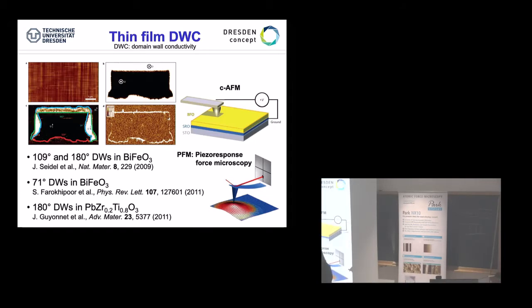This is again the in-plane polarization, and then we have a conductivity map of this one. So he uses two combinations: the PFM that I have introduced and CAFM, conductive AFM. I think Karim has spoken about this, where you take the tip as the top contact, you apply a voltage to the bottom, and hence you have a current passing across your system.